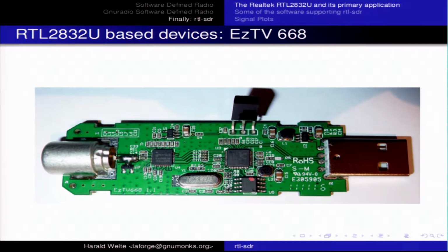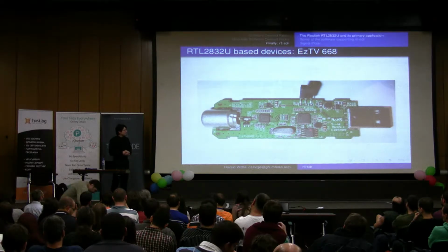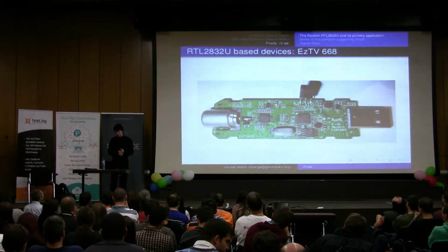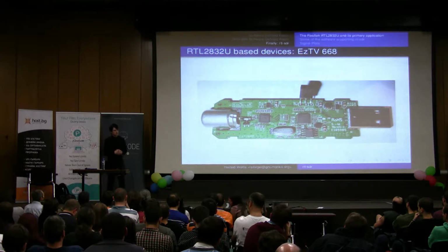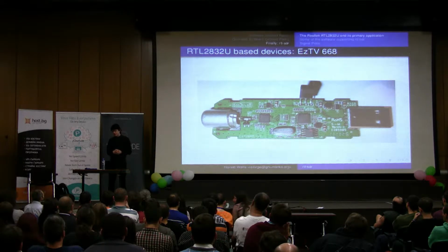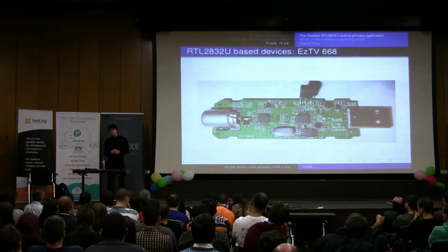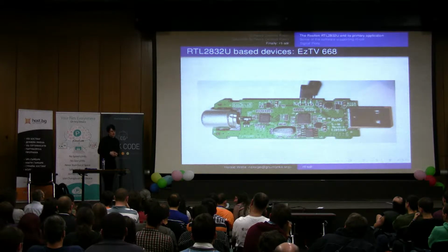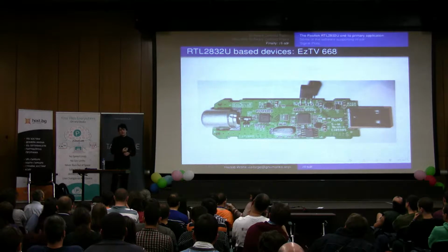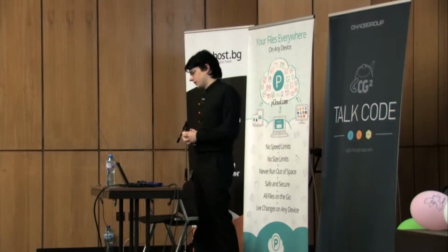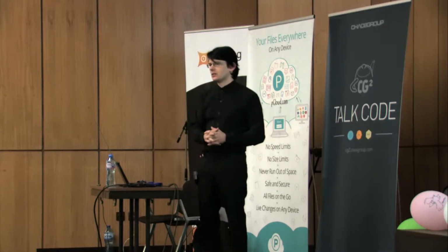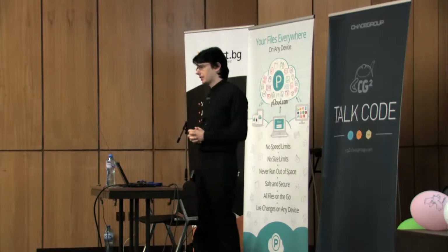So basically, if you put those things together, the open source software and one of these cheap receivers, you have a very powerful radio receiver, and you can use any of the SDR software that is commonly available in open source, particularly anything that's based around the GNU Radio framework, because RTL SDR integrates into GNU Radio as a so-called source, so you can take samples out of the receiver, feed them into GNU Radio, and then you can do whatever receivers are there.